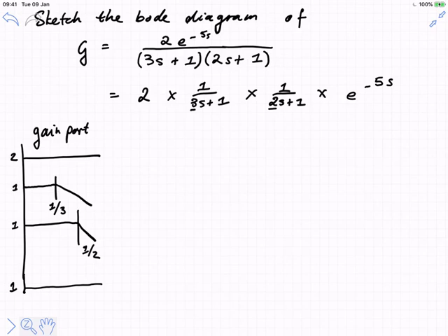Okay, so that low frequency asymptote here is 1, low frequency asymptote here is 1. A useful thing to know about 1 is that the log of 1 is 0. Okay, and so when we plot these on a decibel scale, you'll see these unity gains being at 0. If you just plot it on a log scale, it'll just be at 1. The scale will just be logarithmic. So when we now want to calculate this product, because the log of a product is the sum of the logs, right? That's log rules, okay?